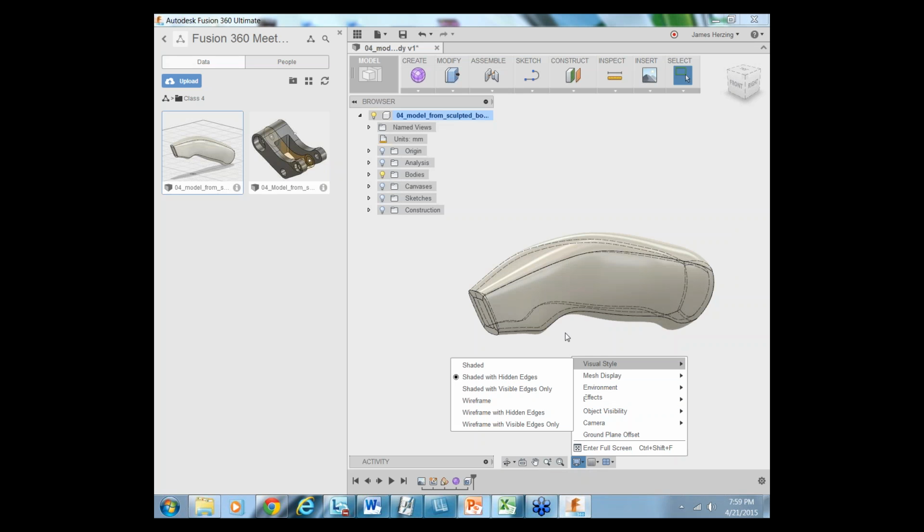We're getting a weird result. Did you choose a face? Okay, escape out of that stuff. Now try it again. Modify shell. So you have a face selected. I have 2 chains. Escape, escape, escape. So let's click on the drop down next to bodies and see if we can do it that way. So now go to shell. There you go. And do 2.